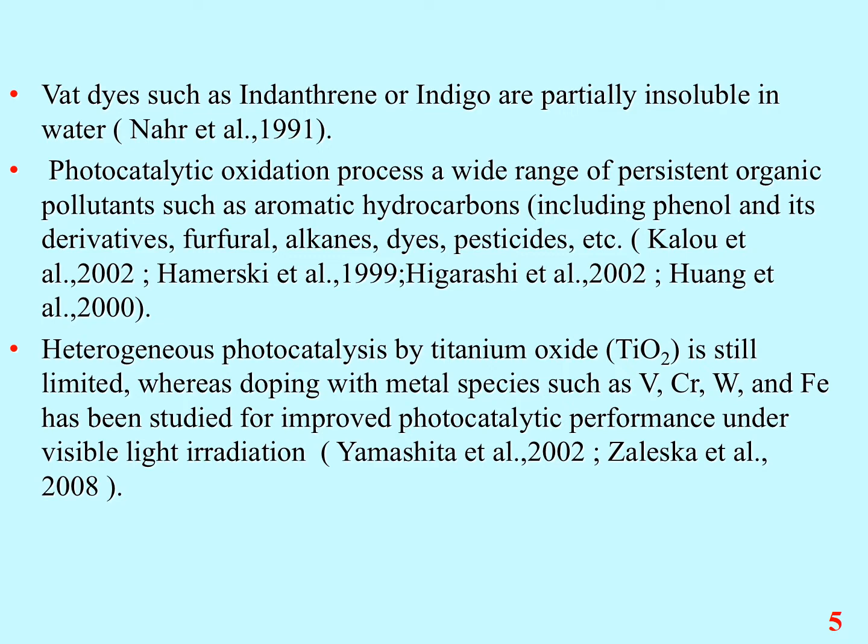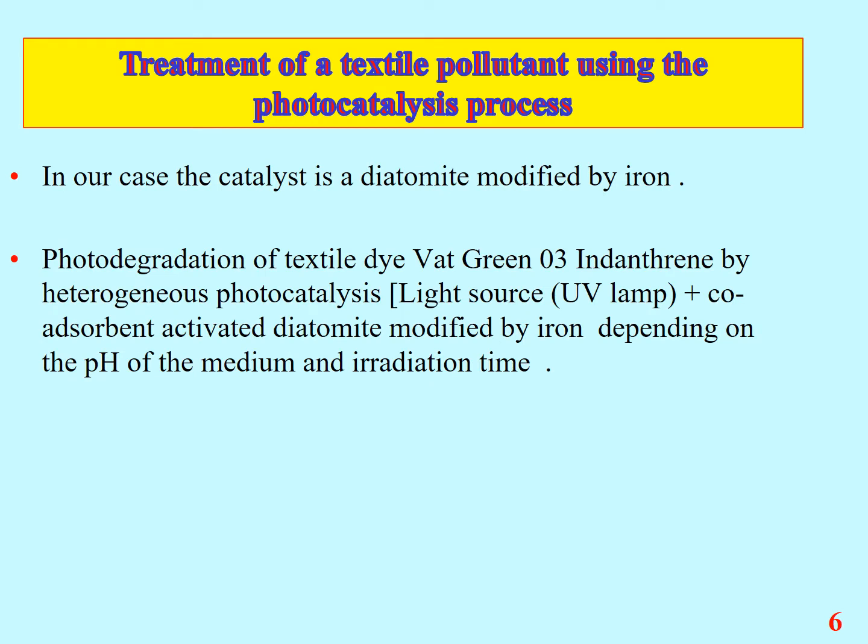Photocatalytic oxidation processes treat a wide range of persistent organic pollutants such as aromatic hydrocarbons, derivatives, furfural, alkanes, dyes, etc. Heterogeneous photocatalysis by titanium oxide is still limited, whereas doping with metal species such as vanadium, chromium, tungsten, and iron has been studied for improved photocatalytic performance under visible light irradiation. In our case, the catalyst is a diatomite modified by iron.